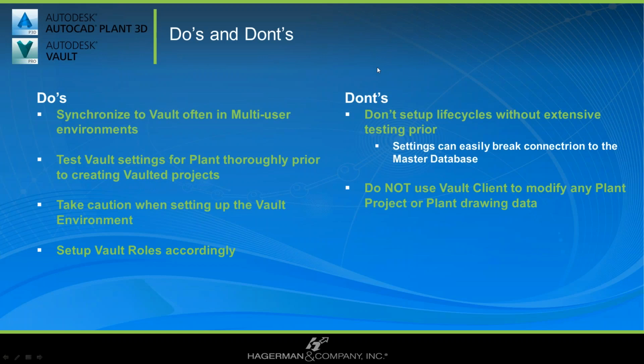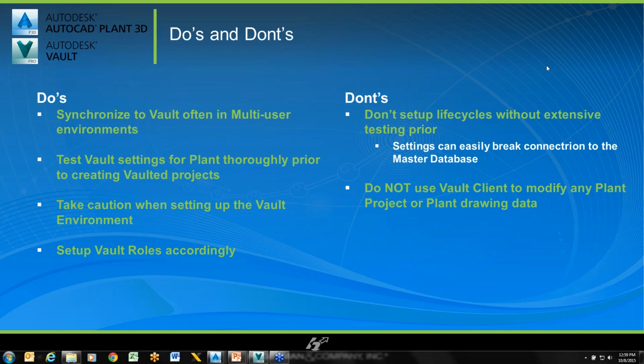Set up Vault roles accordingly to your workflow and staff. Don't set up life cycles without extensive testing. And do not use Vault Client to modify any plant project or plant drawing data whatsoever, whether it's custom properties. Life cycles can break it as well, so definitely try not to modify any plant-related information inside of the Vault client.